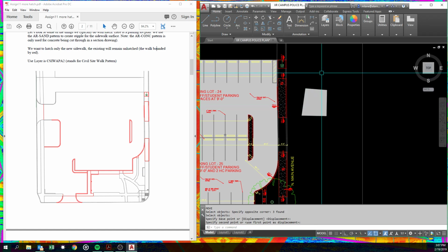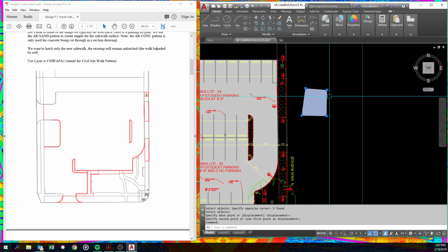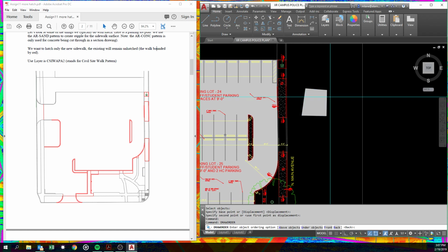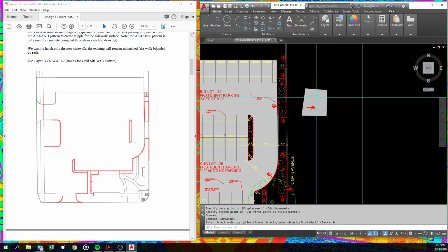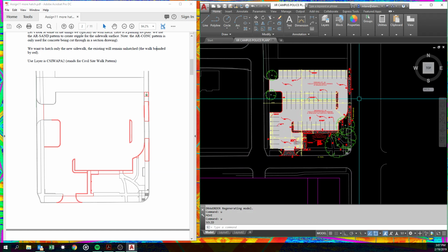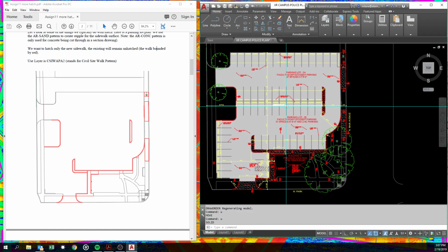over here, how it disappears. That's because this was drawn more recently than that was. So in that case, I'd have to pick this, go to draw order, and hit B, and now it would go to the back. But let's undo all that, because of course I don't want to do that. And then that's this drawing. That's all we're going to do on this today. I just thought you might enjoy fiddling with the real drawing.